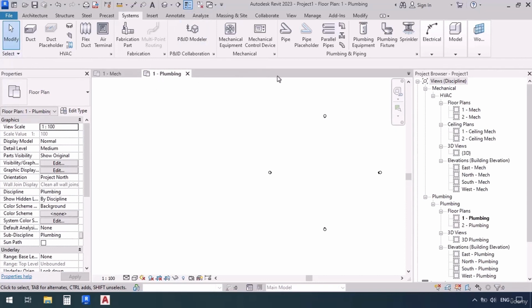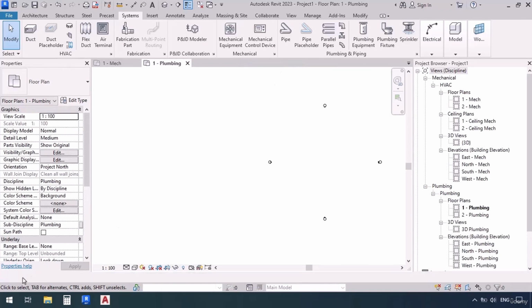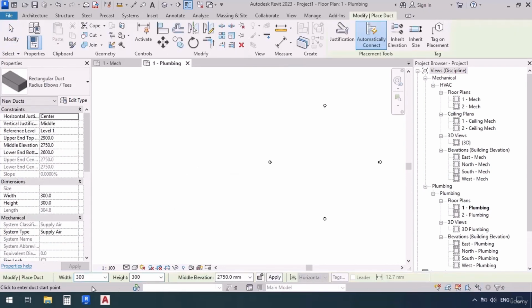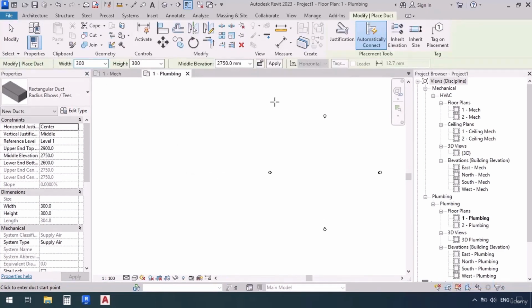You can do this with the options bar as well. As you can see, we have it below the ribbon right now. I can just right-click on it and then click on Dock at Bottom. As you can see, it just moved down. So let me select the Dock shortcut, and as you can see, it's down here. So we could just right-click again and click on Dock at Top, and then it moves back. So it's possible that you may be working with different systems, and you might see that the location of this options bar differs. So remember, this is how you can change its place to where you want.